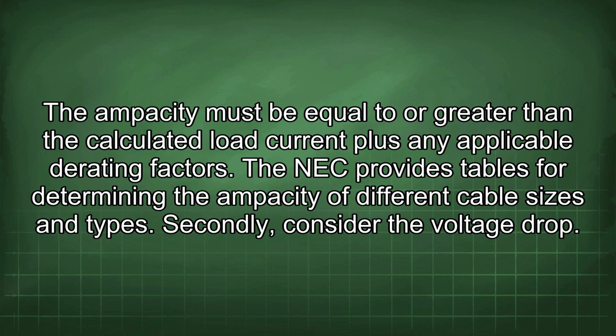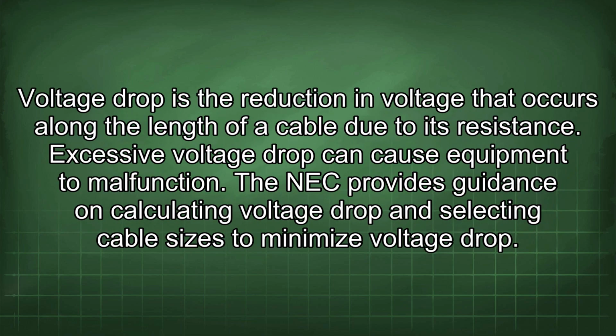Secondly, consider the voltage drop. Voltage drop is the reduction in voltage that occurs along the length of a cable due to its resistance. Excessive voltage drop can cause equipment to malfunction. The NEC provides guidance on calculating voltage drop and selecting cable sizes to minimize voltage drop.